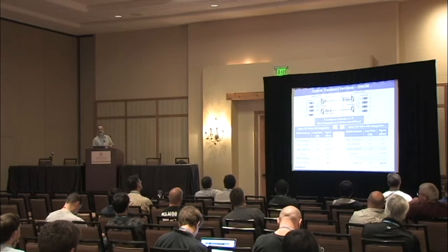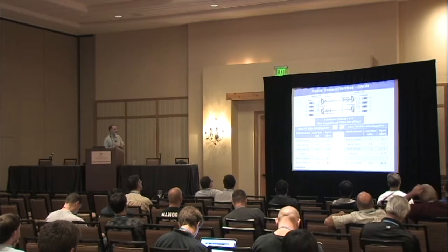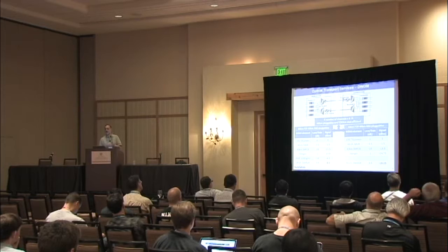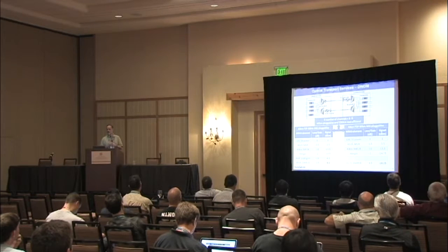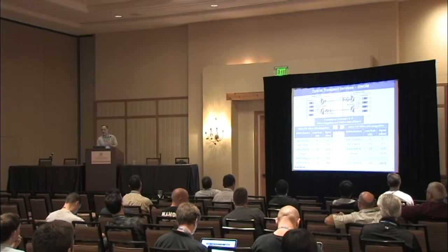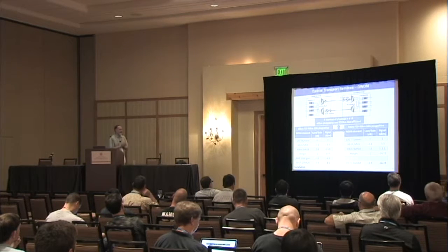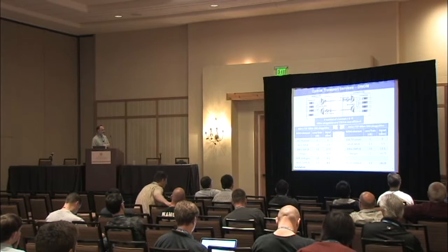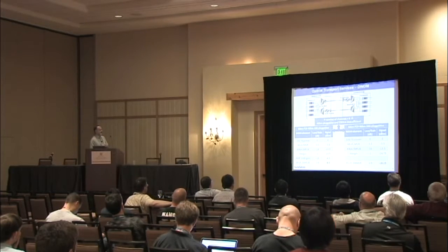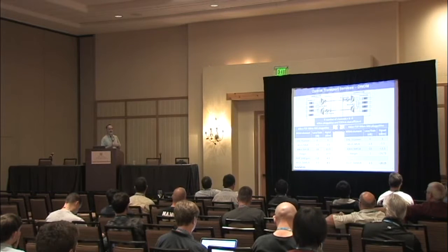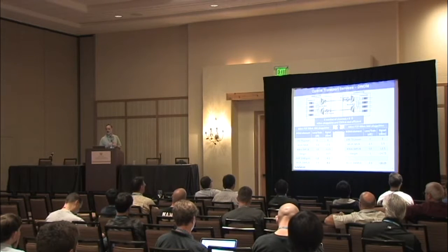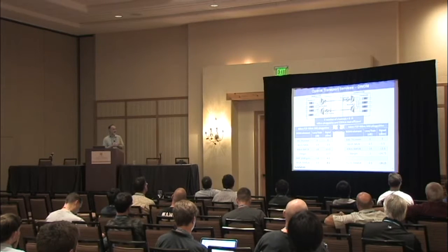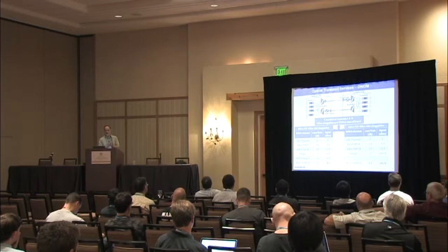Let's look at using 80 kilometer optics, and it's the same calculation. I don't need the amplifier. I'm getting basically to minus 18.25. Keep in mind, 80 kilometer optics have an effective sensitivity of minus 20. So I'm within the range of my 80 kilometer optics. The empirical cost calculation shows that if your number of channels is above 8 channels, you are economically better off using 40 kilometer pluggables and an EDFA.